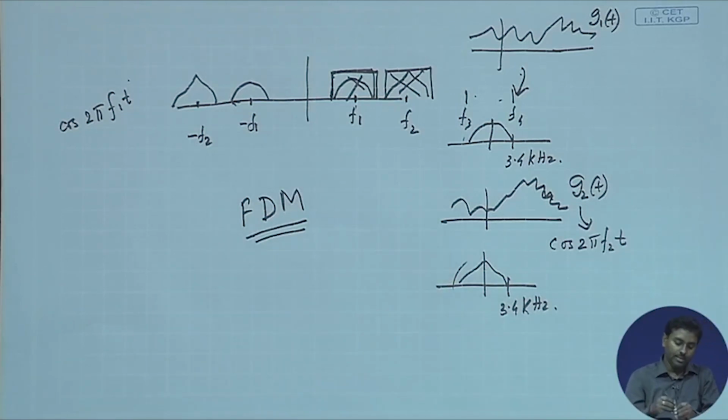Now you can see all these things are so important, because we have an understanding of Fourier series and transform, and because of that we could get another representation of a signal. From the Fourier transform we could derive that there is a property called the frequency shifting property, by which we can keep the signal intact but translate it into a higher frequency. And because we have devices called filters which can separate out some portion of the frequency, we can give a separate entity to each signal in the frequency domain.